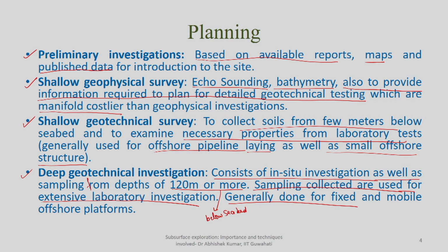So, fixed platform means which are directly transferring the load to the seabed. In that case, considering the load of the overlying structure is too high, you have to go for deeper investigation. If you are going for anchored system, like in case of floating rigs, you can go for comparatively shallower investigations, but more common in offshore platforms.